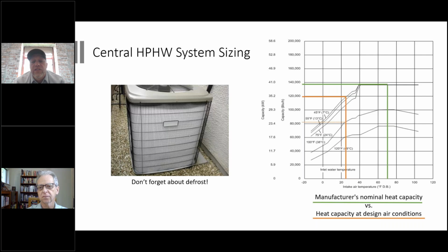So it depends on how you want to size, but you can see the difference between 23 and 19 is somewhat significant. But the sum of that design point capacity becomes what you want to put into the EcoSizer. So if you've got 2 or 3 heat pumps, which would be good design practice, add up all of those at your design condition, and that's what goes into EcoSizer, not the nominal rating size.